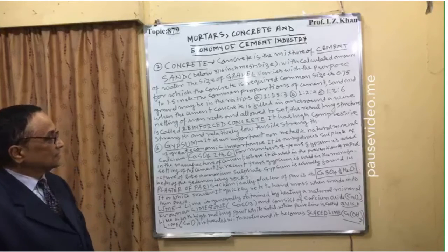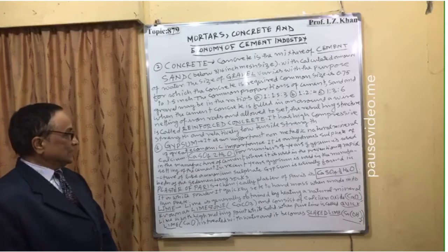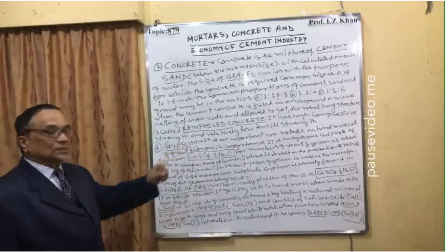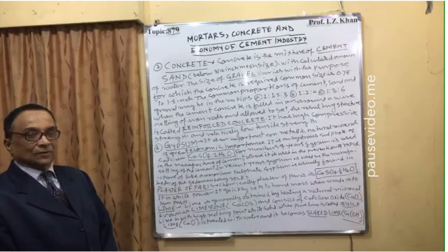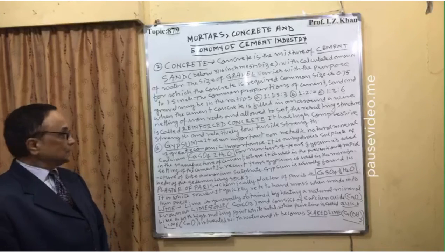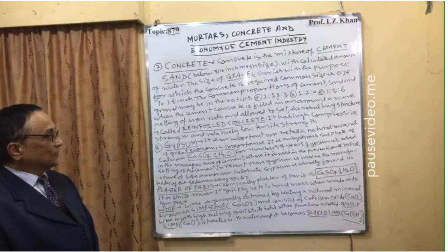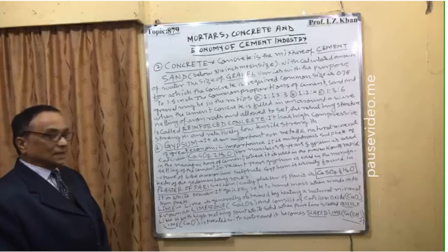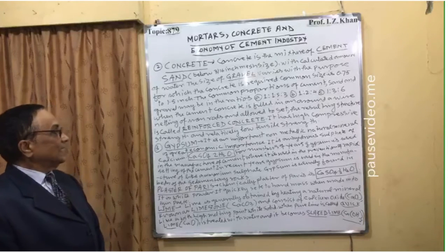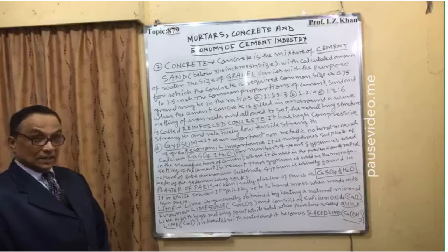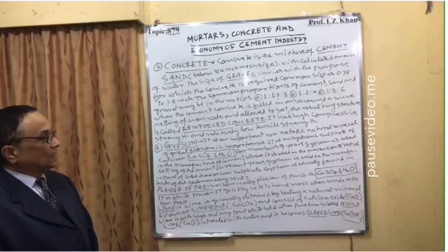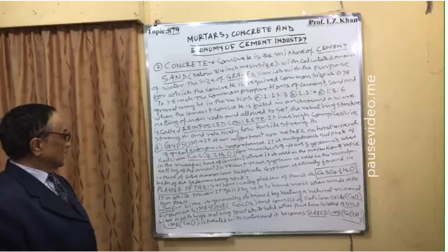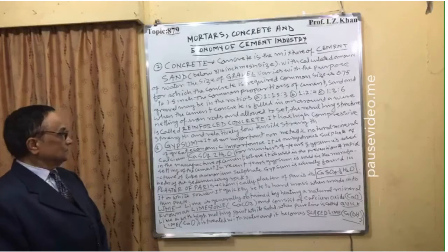It is hydrous sulfate of calcium, CaSO4·2H2O. Once there is water of crystallization with calcium sulfate, it is called gypsum. For a number of years, gypsum has been used in the manufacture of cement, and it improves the quality of cement, where it is used in the prevention of rapid setting of the cement.